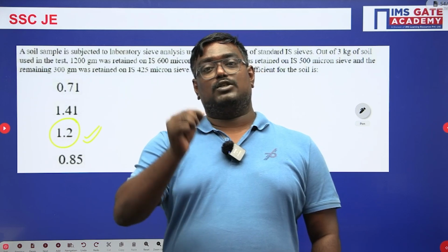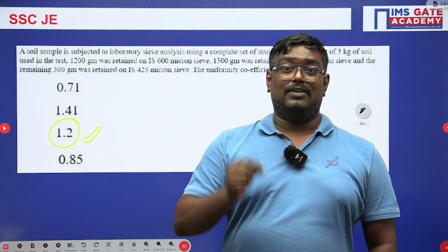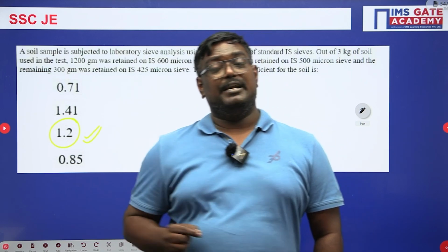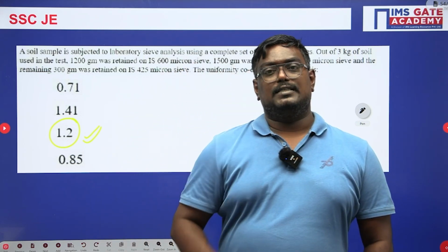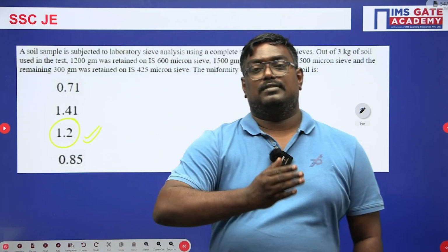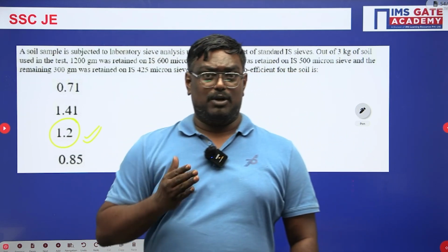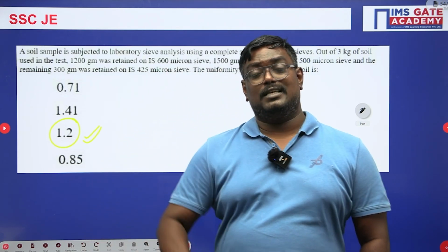And remember, for a soil, if IP is equal to 0, we take it as non-plastic. IP less than 7, low plastic. 7 to 17, medium plastic. More than 17, we call it highly plastic. Consistency index is given by the formula (WL minus W) by IP. Similarly, liquidity index is (W minus WP) upon IP, and remember liquidity index plus consistency index is always equal to 1.